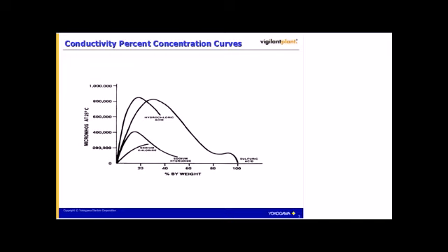Another key industrial use for conductivity measurement besides pure water is for processes with much higher conductivity values. Here we are determining the chemical strength or percent concentration of a solution. There are 3 factors we need to pay attention to in order to successfully make this type of measurement. The first, that each chemical responds differently from the next with regard to its conductivity value versus percent concentration level. Often the difference is significant, but sometimes it's not. These differences have to do with the size and mobility of the ion of each chemical.